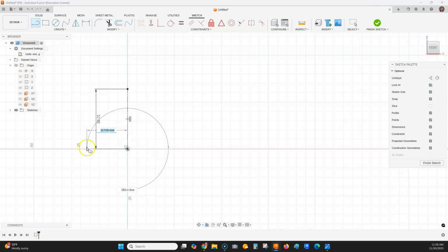I'm just going to go over. It doesn't really matter how far we're going here. I'm going to go over and go up, go over again, and come up. I want to make sure these don't line up, so I don't want to snap here. I'm going to click and come up, and I want to reference just this line right here. I'm going to click, and we're going to come over just a little bit, drag straight down and click when it becomes vertical. You're going to see that we now have an area over here. When I see this light blue area, what Fusion is telling me is that I see a place where I could revolve or extrude.